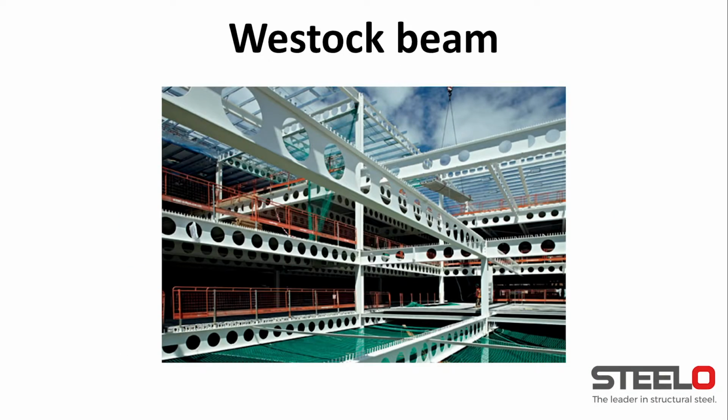A Westok beam is a beam made by a company called Westok, and they've patented their beams, so basically they have these massive holes. The way they're made is that it is a smaller beam, but then a laser cuts the web in such a way that when you put one part on top of the other and shift it slightly to one side, you end up with these kind of shapes where you have a nice hole in the middle of the beam. You use them to save weight, but also to increase the depth of the beam, which obviously increases the strength capacity.